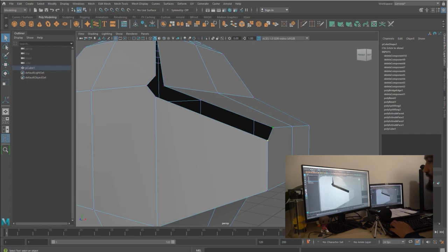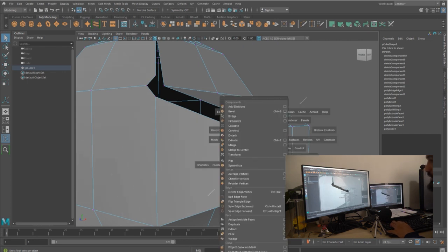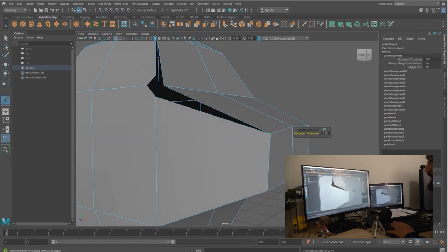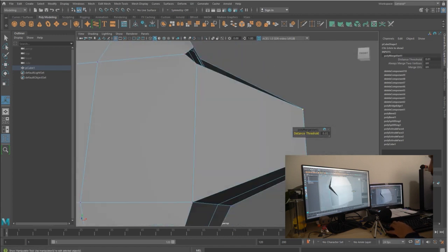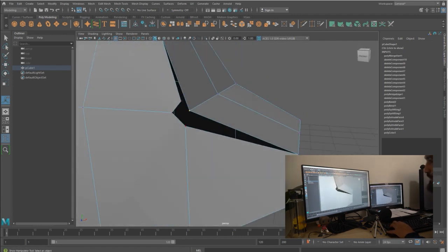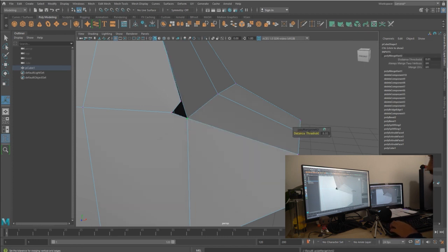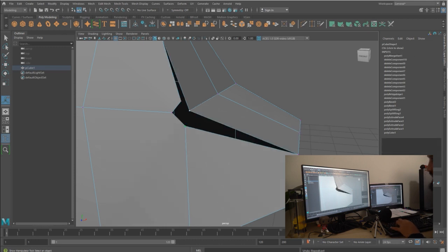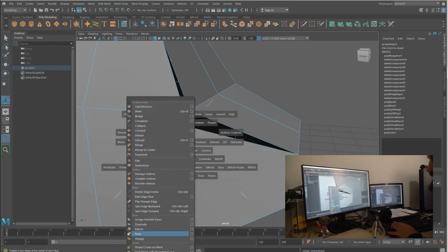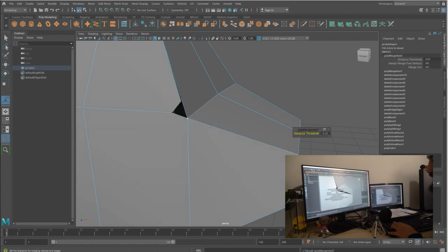And now we want to connect all these to make the same look as this one, okay? So we're gonna take the two vertices here and go in what we call the merge tool. The merge tool is for merging two vertices. So now it becomes one, and it can be helpful for multiple reasons. Here we press G. G is the last action used, G like Google. And if you don't, you can just go here, edit mesh, and merge.